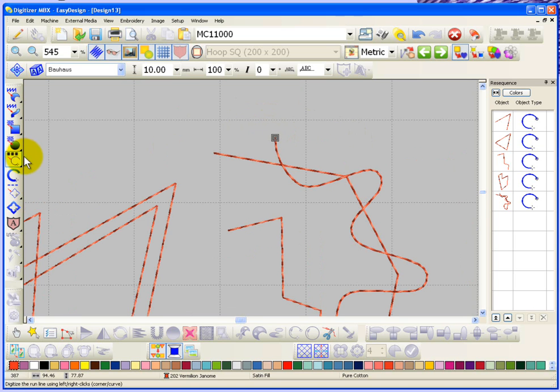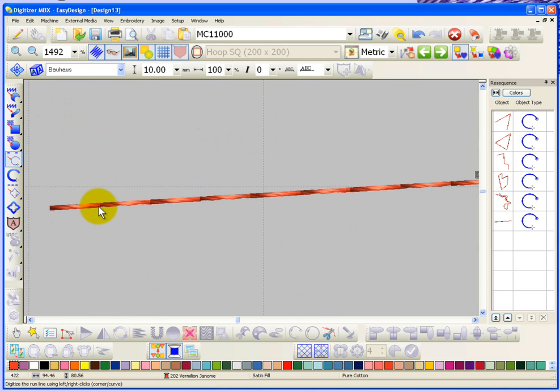And you have another option under the line tool, and that would be the sculpture run line. And again, I'll just draw a simple line here and hit enter. And with the sculpture run line, the way the stitches go, it's forward, then forward, and forward a 3rd time, then backwards 1 stitch. Forward, forward, forward, back. So the idea is you end up with 1 stitch that's done single, and the next stitch which is done triple. And it gives sort of a handmade stitch look to the sculpture run line.